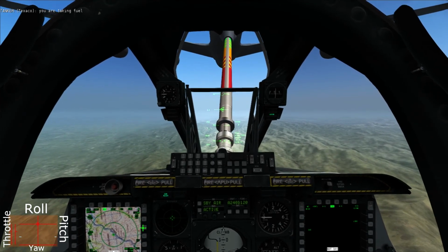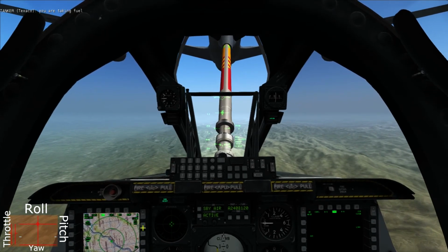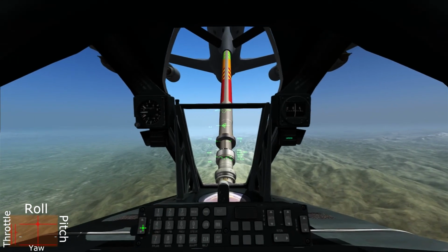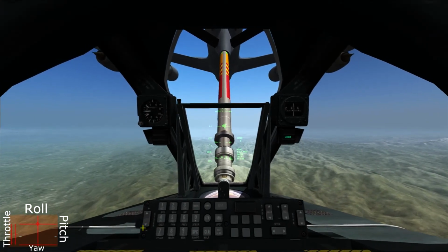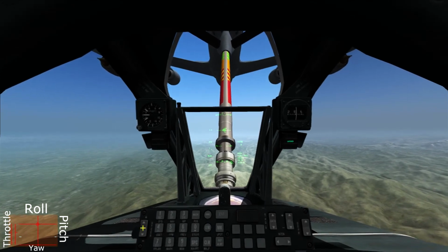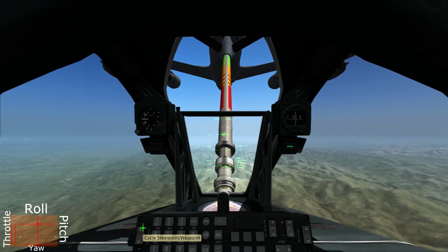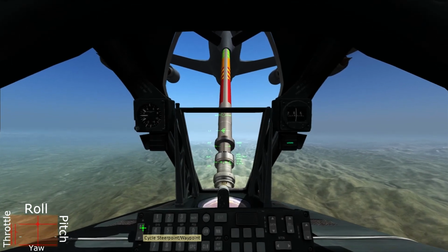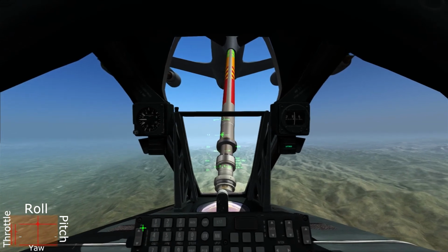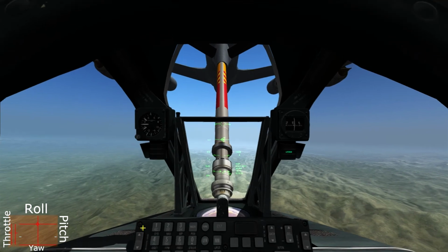And so now you can see we just need to maintain that position. So what I like to do to maintain the position is put the boom, the bit with the wings on it, that bit at the top of the screen, right where it is right now. So the 2 wings are in the corners of the top of my front windscreen, and I like to keep the distance, so the green marker on the boom, around that point, and that will give you an accurate representation of where you need to be.